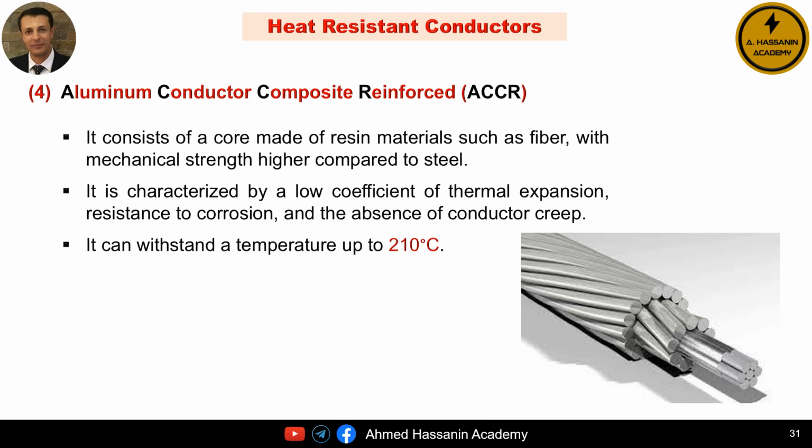It is also characterized by having a low coefficient of thermal expansion, meaning that it does not expand during summer or high temperature conditions and does not contract during winter or low temperature conditions. Another important advantage of this type is its high resistance to corrosion. These conductors can continuously withstand temperatures up to 210 degrees Celsius.